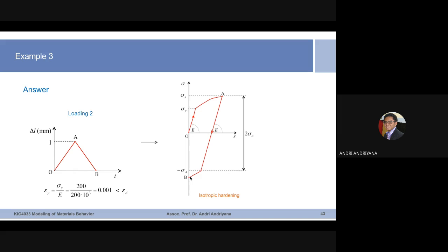Now, here's the thing. It depends on the characteristic of metal. Because we deform plastically the materials, a strengthening phenomenon occurs, which is called strain hardening. You have learned it in material science. Okay, so the fact that here you load the material to the stress level at point A, you deform it plastically, you increase the strength of materials. Okay, when you increase the strength of materials, what is the consequence? The yield strength will increase.